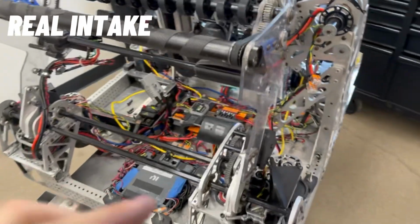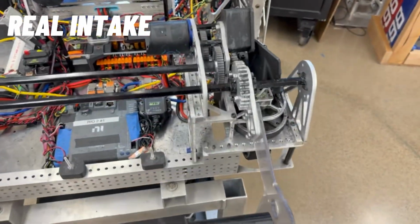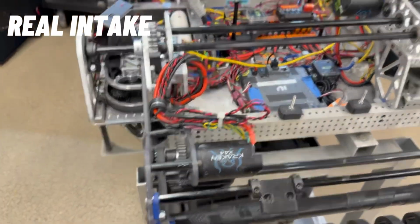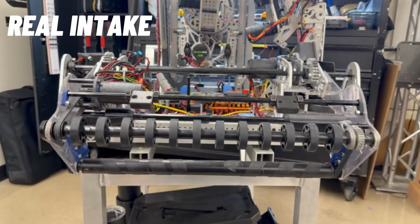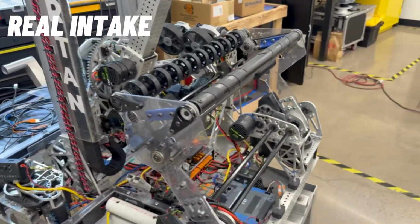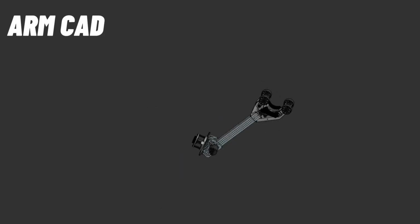Here's our intake. At the core, we're running a high gear reduction into a custom 10 DP tooth gear plate that drives this system. We also carry a high reduction into our intake rollers, which allows us to use a smaller Kraken 44 while still driving consistent torque and controlled pickup. Next is our robot arm, designed with a full 360-degree range of motion.